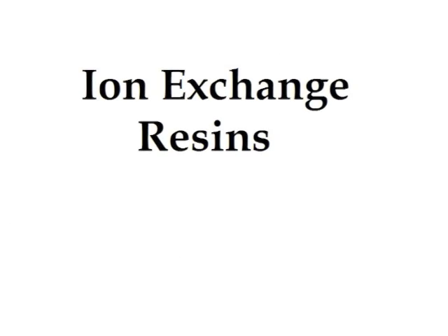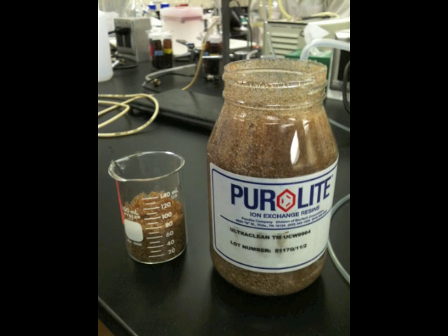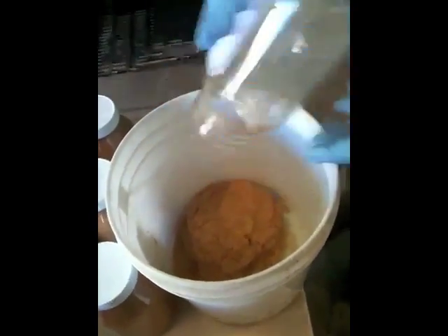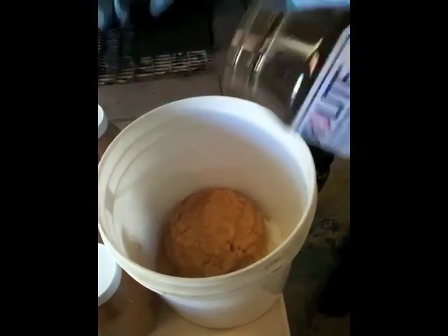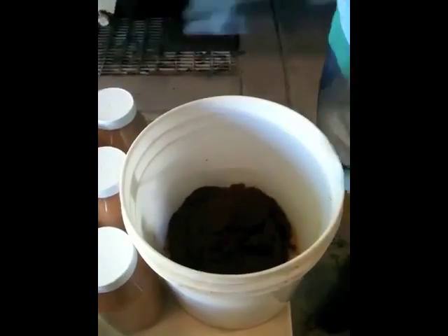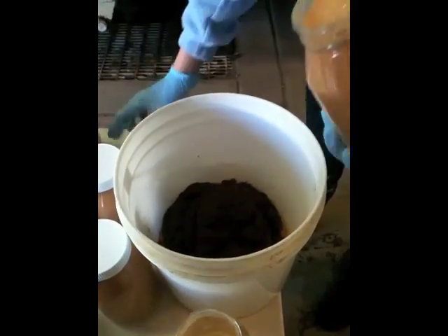Ion exchange resins. Selecting the right ion exchange resin is of the utmost importance to the success of the unit. Because we are removing ions from the water, it is necessary to select resins with hydroxide and hydrogen functional groups. The unit will be a packed bed column, so the resin should be of a gel polymer base as well. Resins from Purolite were selected by the team.